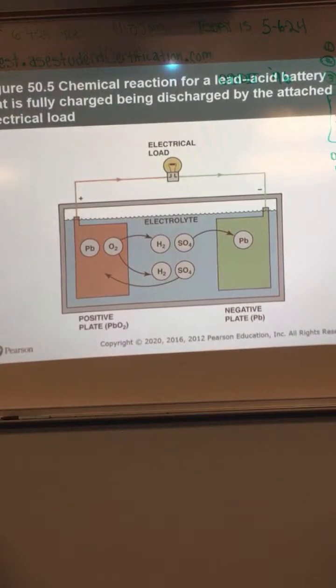It can happen. That's why they tell you when you jump start a car, make that last connection on the negative away from the battery, because it's going to create a spark as soon as you connect that last cable. Okay? Most cars have jump start terminals on them anyway that are away from the battery, so you don't have to worry about that spark.